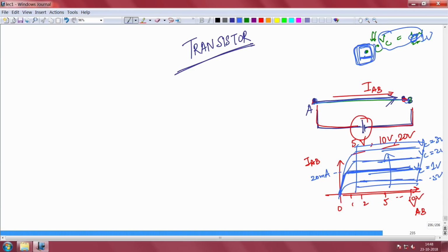A transistor can have many functions. It can act as a switch, which means whether current flows here or not, I will determine by this terminal. I can choose to have no current flow here, no matter what voltage you are applying. You might apply 100 volt between this point and this point, still get no current. Why? Because you are controlling that flow by the third terminal. In that case, a transistor can behave like a switch.